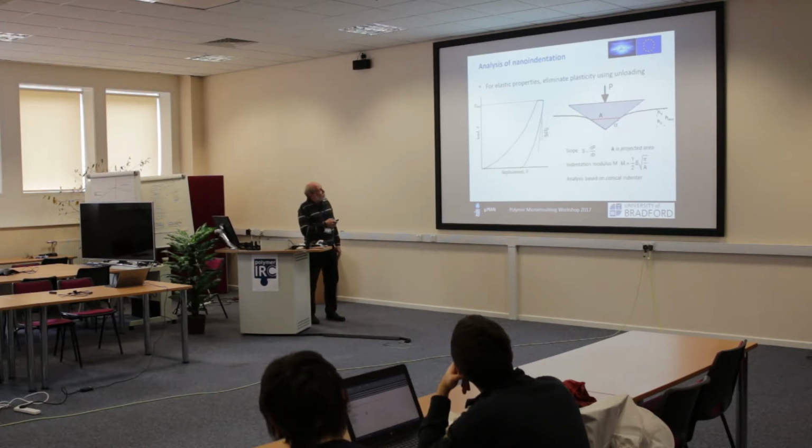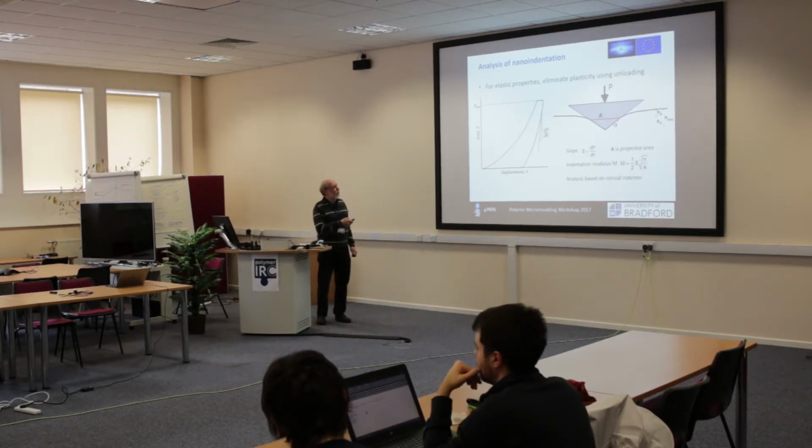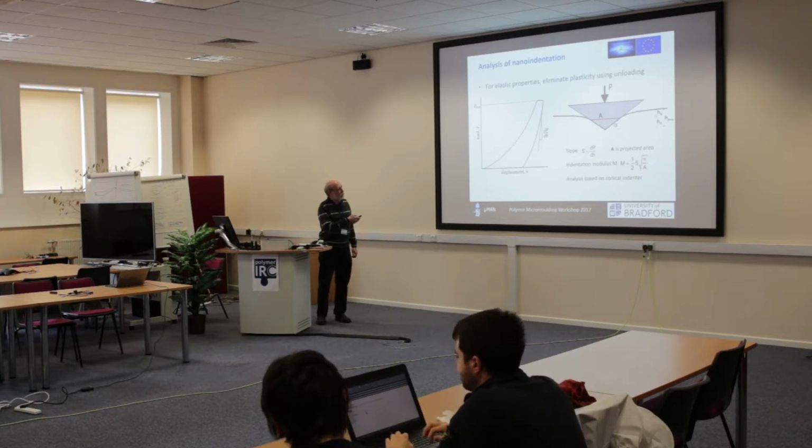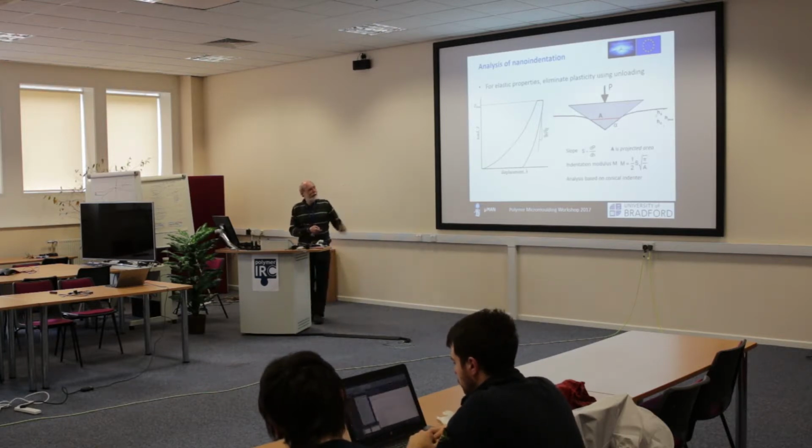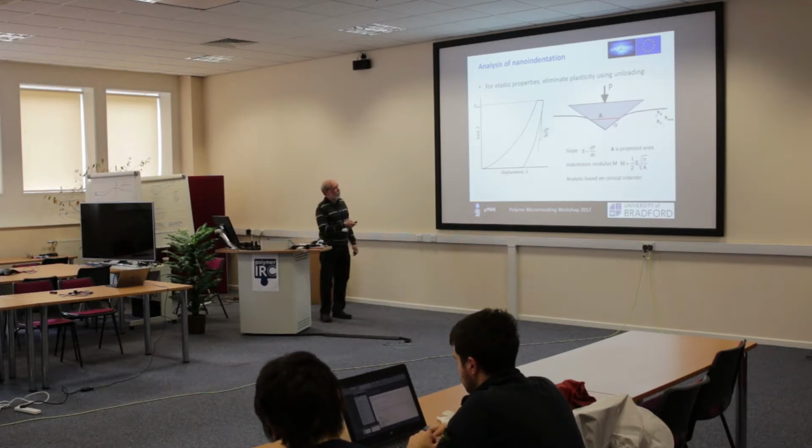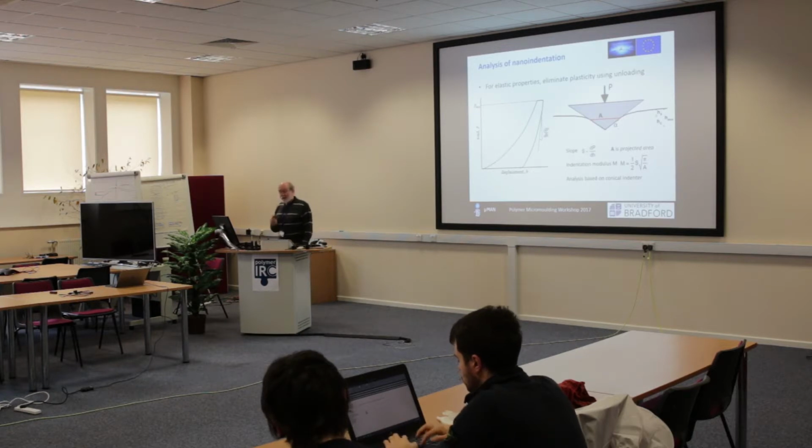Whereas when you stop and unload, then you withdraw the indenter, so you're not actually creating any more plasticity. So all the forces you see as resulting from this unloading are because of elastic recovery. So this unloading is really a way of isolating elasticity. So then you can measure something.